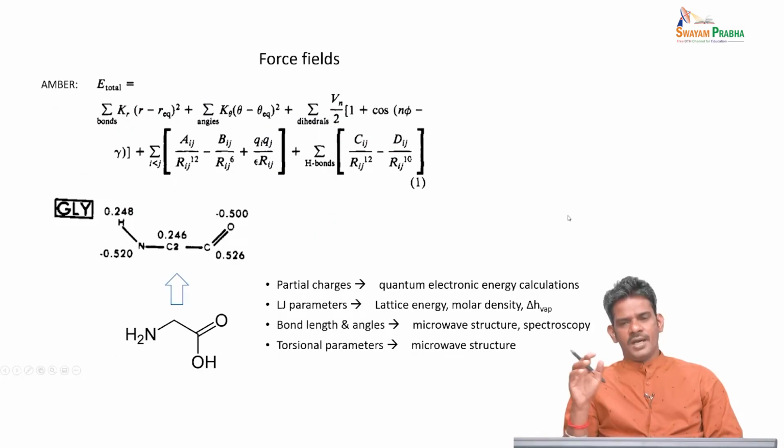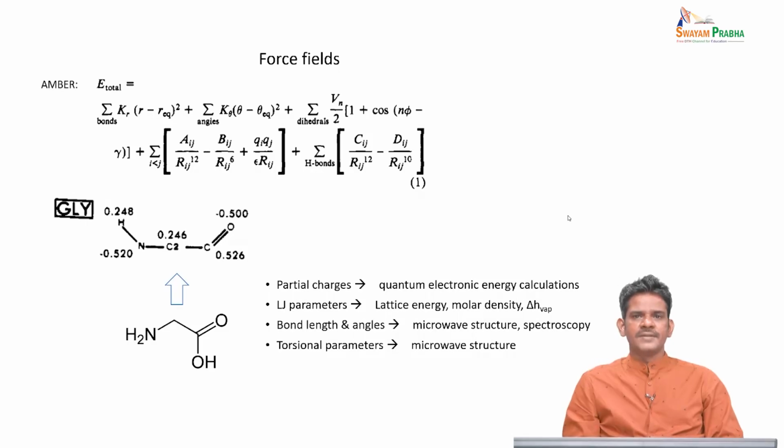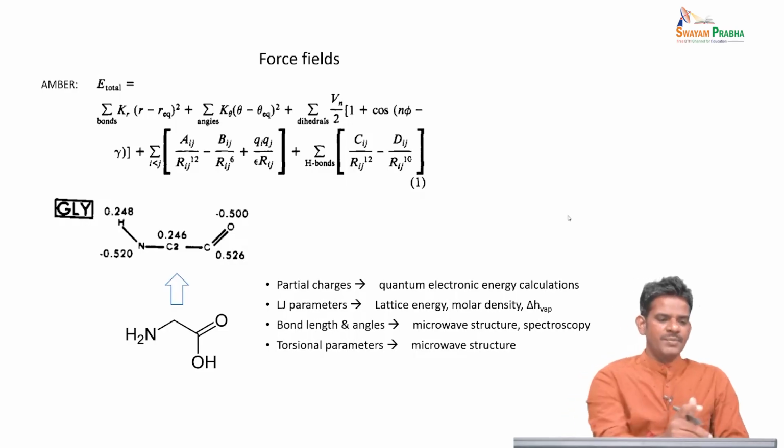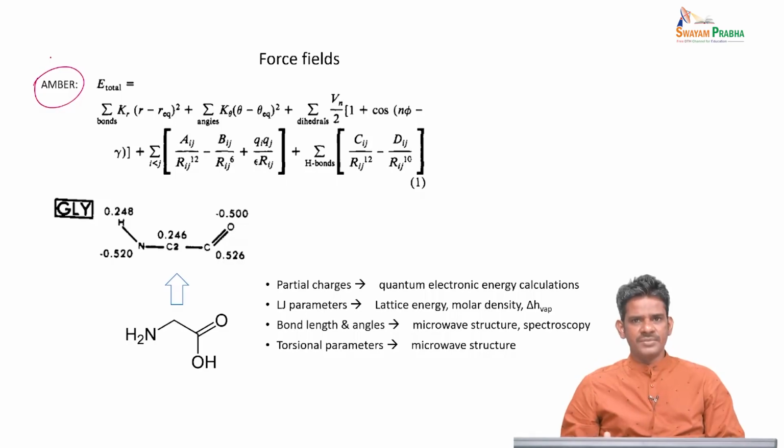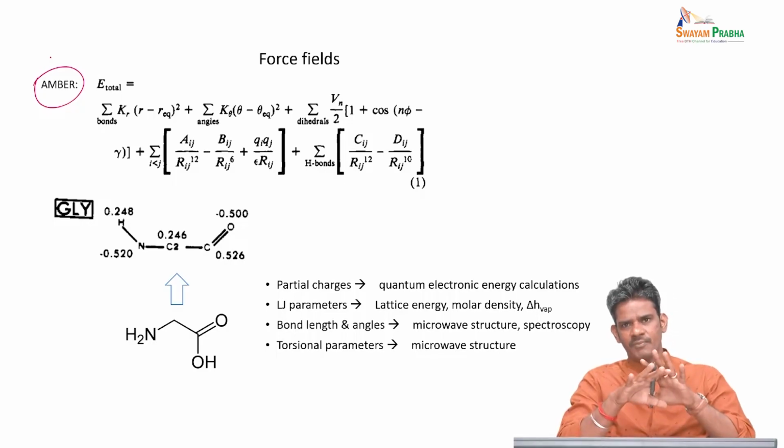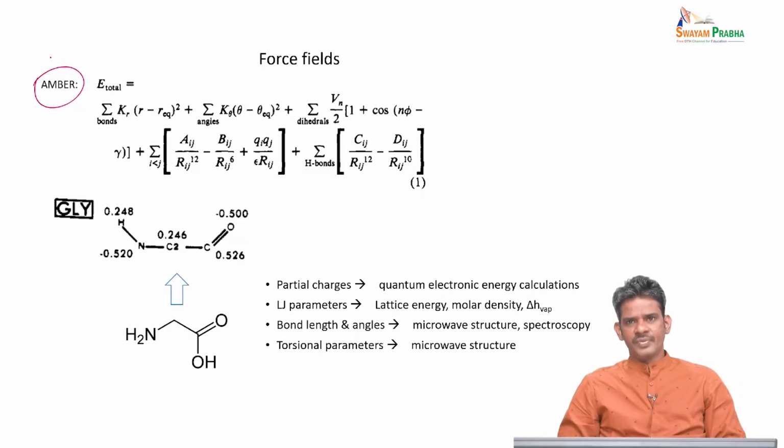So moving on, as of now, if you go to any MD simulation package like LAMMPS or GROMACS, you don't have to worry about building all this model. It's already done there for you. For example, here I have taken the Amber force field. There are many other force fields: CHARMM is there, OPLS, and so on. If you look at the manual of these potentials or force fields, they will give you a full potential mapping, what kind of functional form each force is taken into.